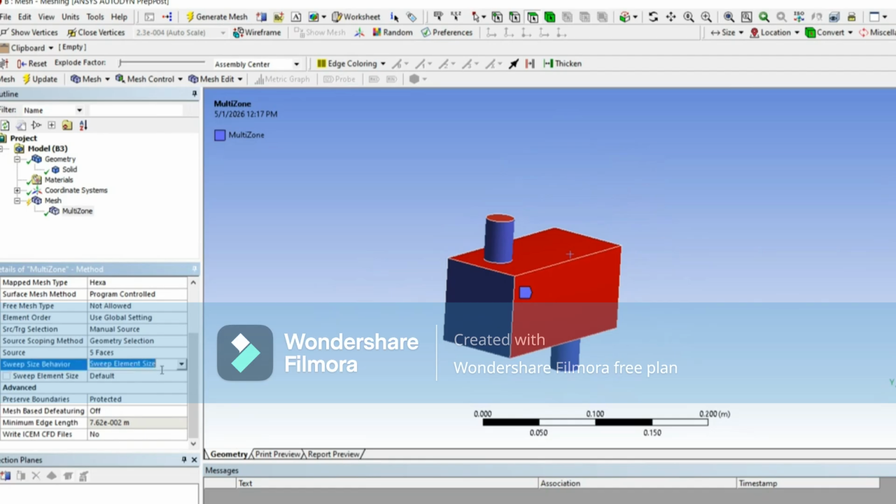Then you can also give the size behavior, like what should be the side faces. That part you can control later on, like what should be the element size. So you can control it from this part. If you want a finer mesh, you can give a smaller element size, so that you have a finer mesh. And then generate the mesh.